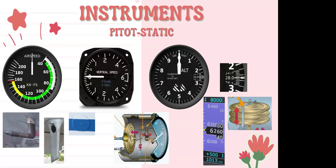Now, when you level off from that climb, there's no more change in air density or air pressure, right? Because we've leveled off. And so it will, after about 7 seconds of lag, equalize. Now we have the same pressure in the case as we do in the diaphragm, which will then show a 0-foot-per-minute climb.